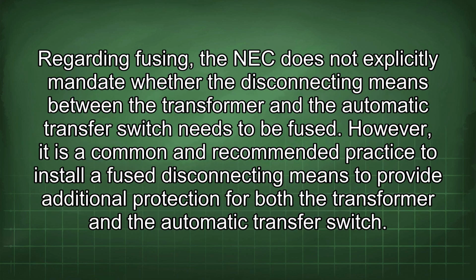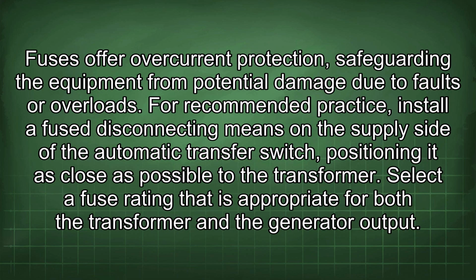Regarding fusing, the NEC does not explicitly mandate whether the disconnecting means between the transformer and the automatic transfer switch needs to be fused. However, it is a common and recommended practice to install a fused disconnecting means to provide additional protection for both the transformer and the automatic transfer switch. Fuses offer overcurrent protection, safeguarding the equipment from potential damage due to faults or overloads.